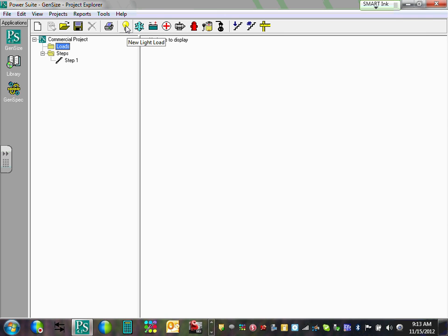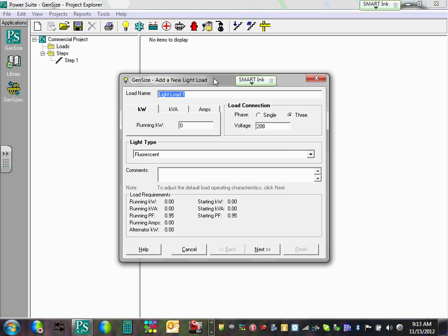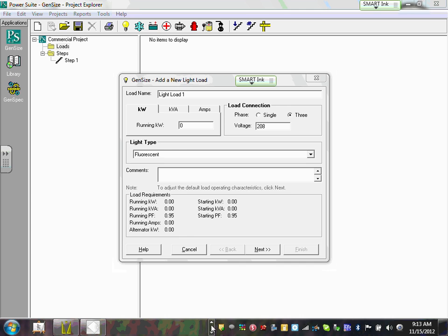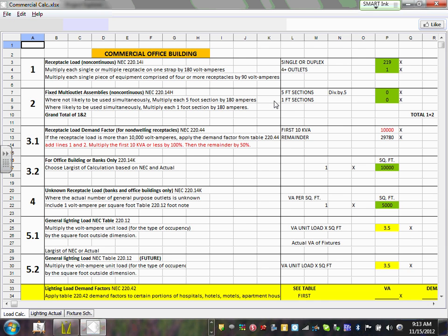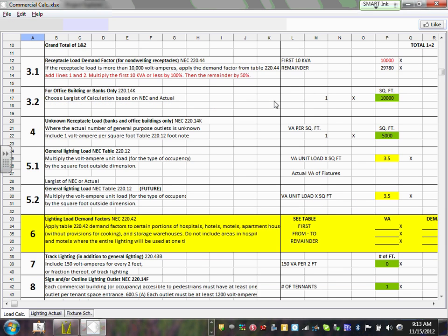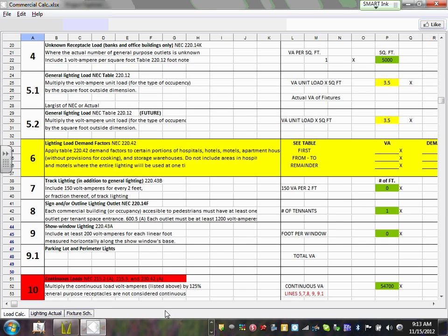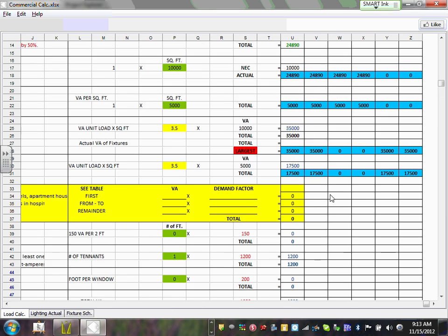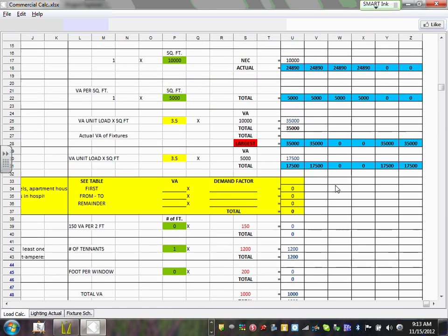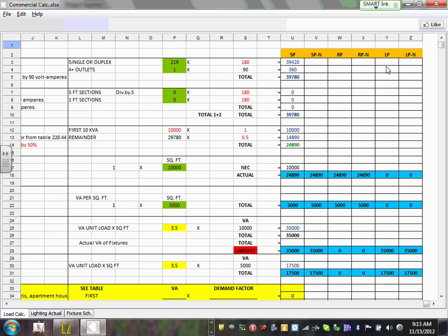Can you see this bulb? Anybody can see what this type? This is light, right? Click on this. It opens the window like this for you. Okay, before you go anywhere, let's go to your load calculation. Jeff, I'm going to go steal your lighting panel load. Remember you sized the lighting panel for me? The kVA. What was the kVA? Go to your load. Here's Jeff's lighting panel load right here. I'm going to go steal his lighting panel load.